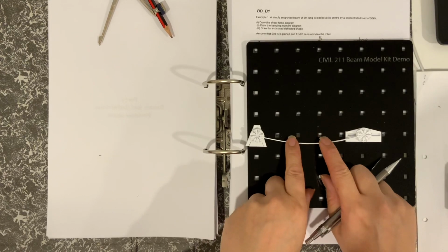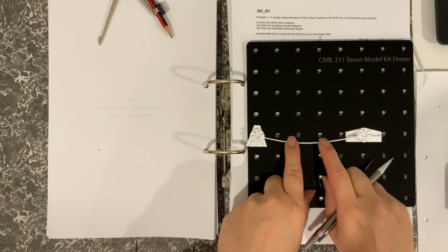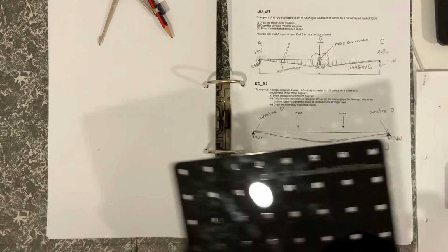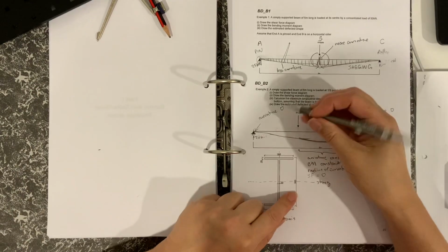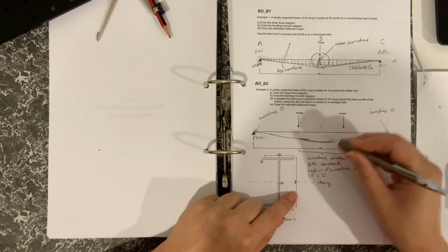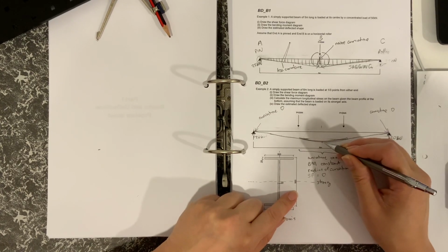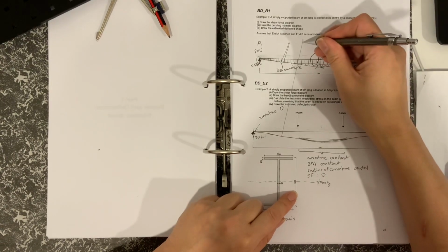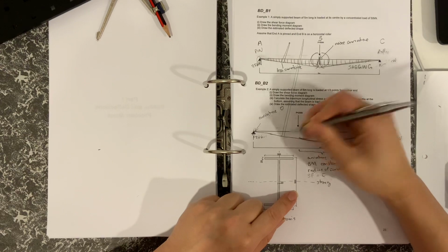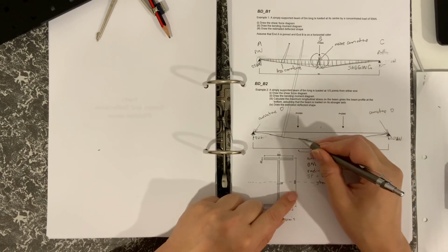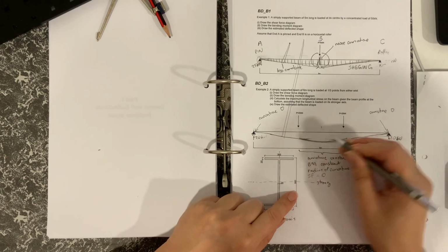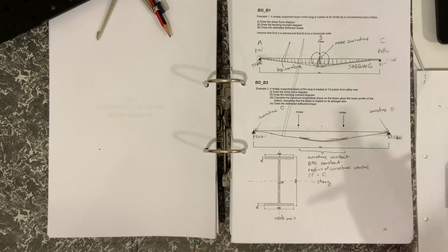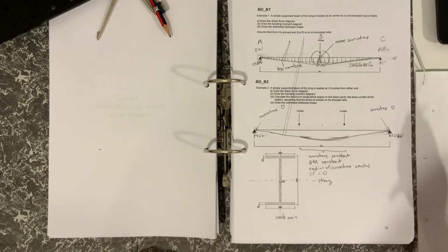So again, I'll try and illustrate it on the model. So I think you can see the biggest curvature would be between my two fingers. So we could say that the radius of curvature here would be bigger than the radius of curvature here. Okay, so the radius of curvature here may be something like that. Obviously the radius of curvature would be changing because the bending moment diagram is changing, but the bending moment diagram is constant between these two points. And when you reach the end, then the curvature is 0, which means that the radius of curvature is infinity.